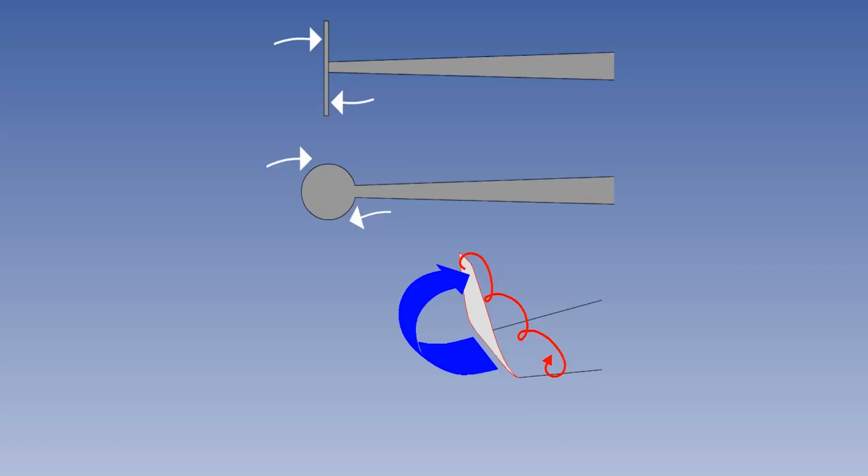The small vortex created by the winglet also interacts with and further reduces the strength of the main vortex. Finally, simpler variations of wingtip shape, such as turned up or turned down tips, can be used to reduce induced drag. Vortices are weakened by the blocking of airflow from lower to upper surface round the wingtips.